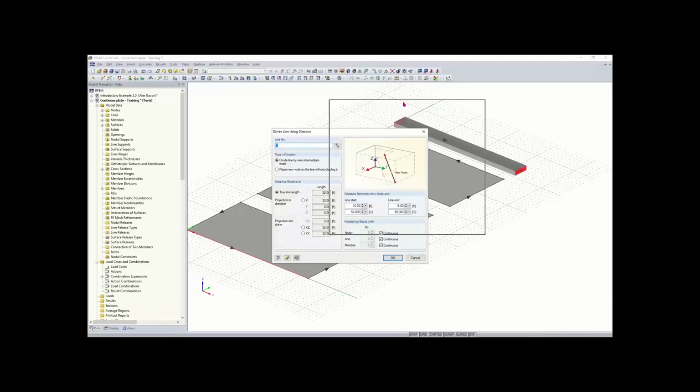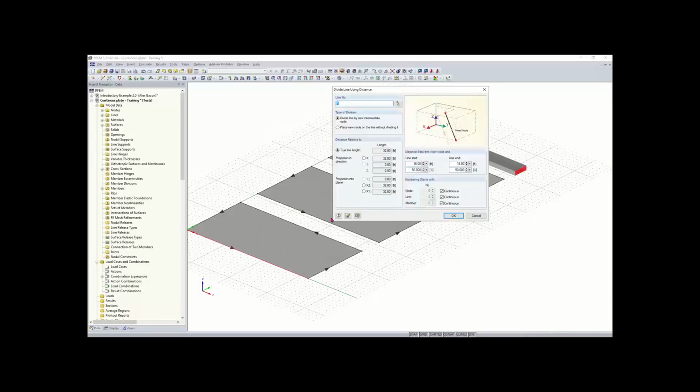And you can see when I pick that divide line option, we have these gray arrows here on your lines. And these arrows tell you the orientation of the line or the direction that you drew the line. So this would be the start, and this would be the end of the line. You can also view these arrows by just hovering over any line that you've drawn.